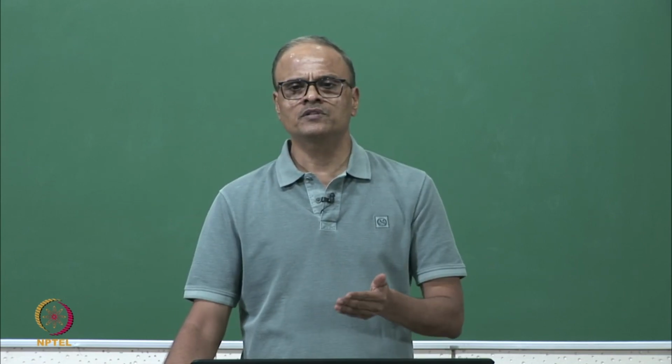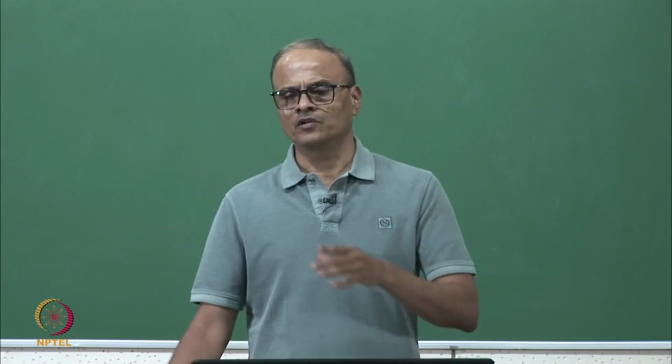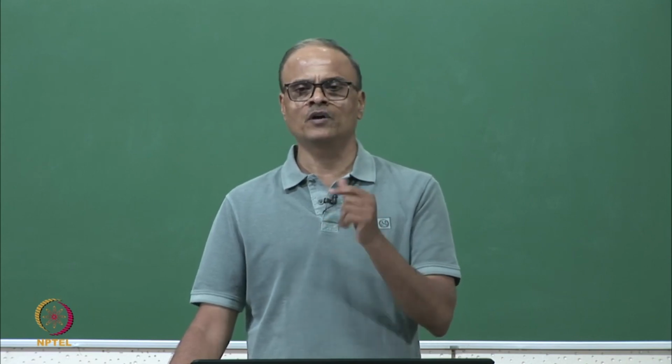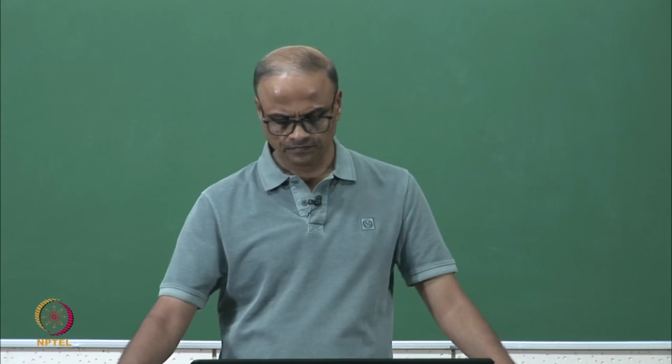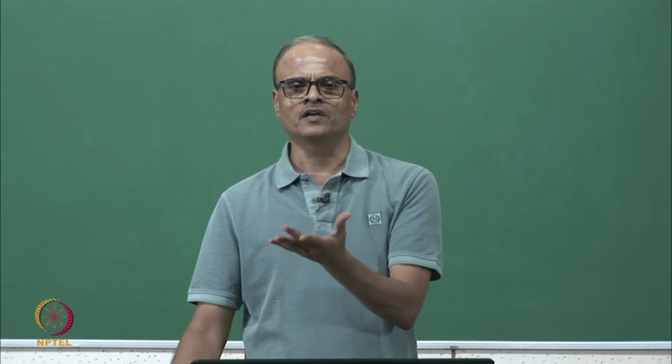So, several approaches have been proposed which can be used to decide the modal order, or the number of modes which we want to identify through modal parameter estimation. The first approach has been to count the number of peaks in the FRF. This is probably the most straightforward thing to do: we look at the FRF of the system and then we count the number of peaks in the selected frequency band.